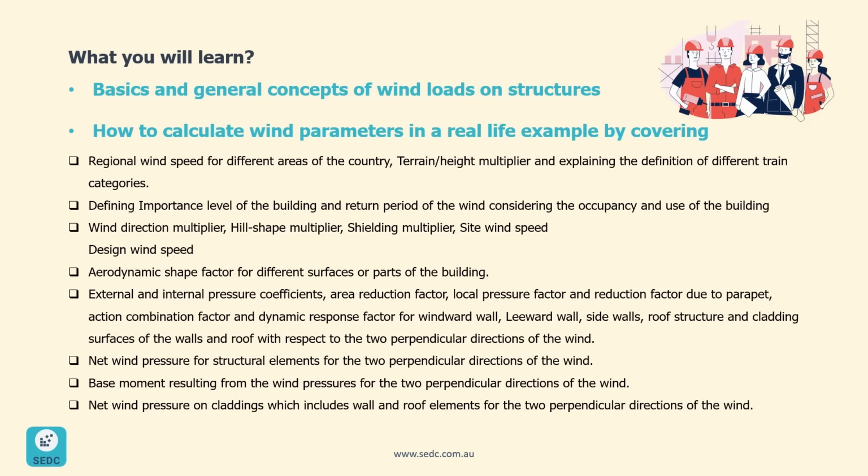I also talk about aerodynamic shape factors for different surfaces or parts of the building. Calculating aerodynamic shape factors requires calculating the external and internal pressure coefficients, area reduction factor, local pressure factor, and reduction factor due to parapet, and also action combination factor and dynamic response factor.